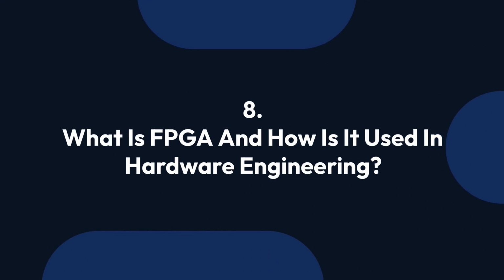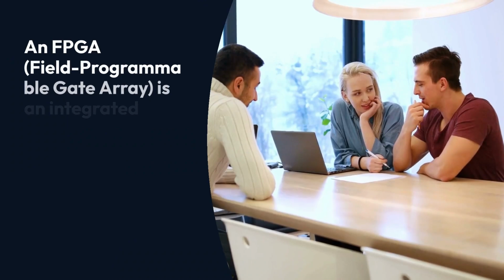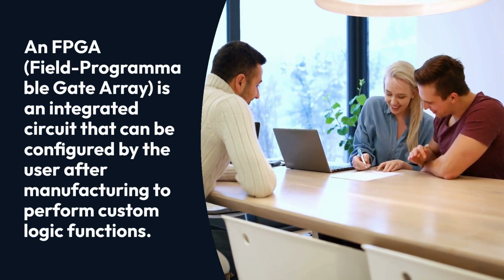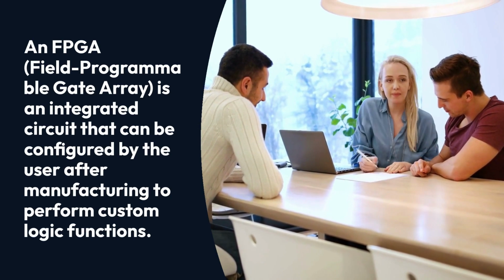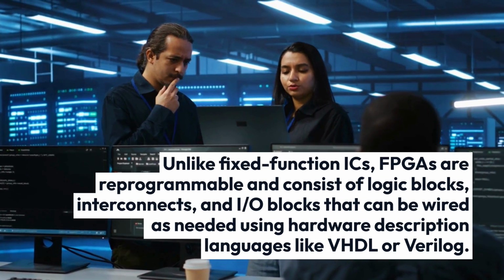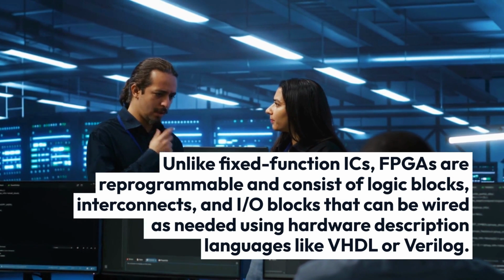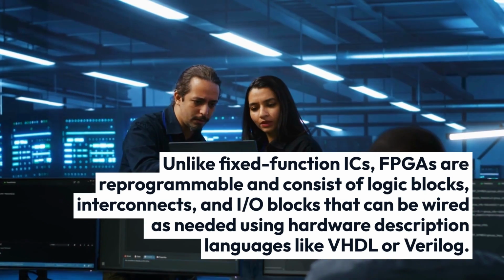8. What is FPGA and how is it used in hardware engineering? An FPGA, Field Programmable Gate Array, is an integrated circuit that can be configured by the user after manufacturing to perform custom logic functions. Unlike fixed function ICs, FPGAs are reprogrammable and consist of logic blocks, interconnects, and I/O blocks that can be wired as needed using hardware description languages like VHDL or Verilog.